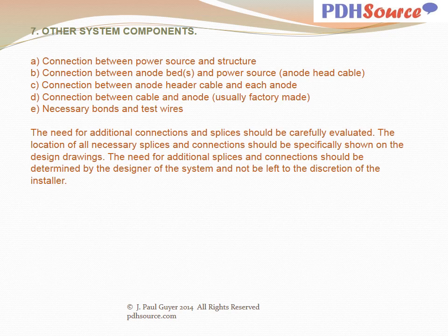The need for additional connections and splices should be carefully evaluated. The location of all necessary splices and connections should be specifically shown on the design drawings. The need for additional splices and connections should be determined by the designer of the system and not left to the discretion of the installer.